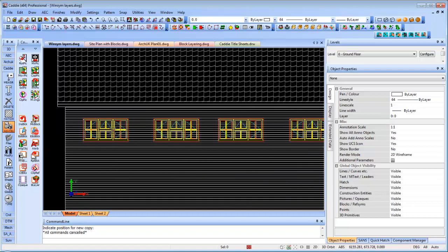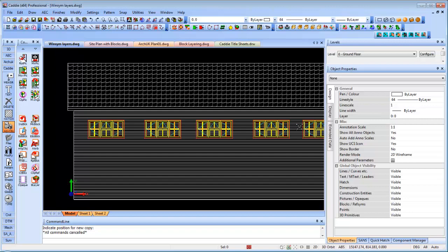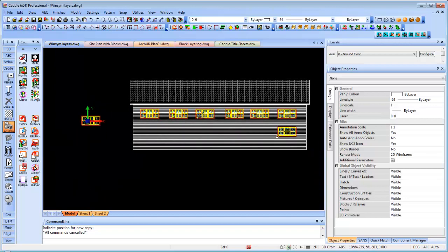So we have here, instead of 143 objects times 1, 2, 3, 4, 5 and so on, effectively just 1, 2, 3, 4, 5, 6, 7 plus the original 143 and that one. So that would be 8 plus 143 rather than 143 times 8 objects. So you can see that our drawings have the potential to get much smaller, much faster.